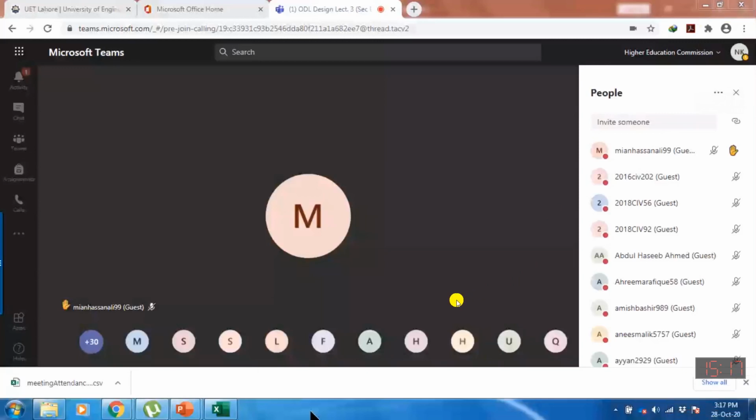You can download it, there are a lot of tutorials available. It will be quite easy. You just need to construct the truss in the software, and then apply the unit joint load. When you apply it, you will have the member force for each gravity load. So it is up to you.